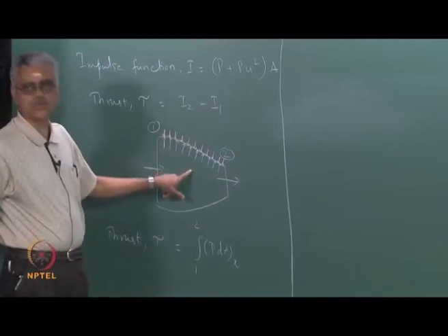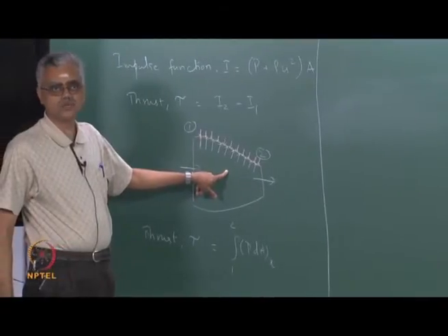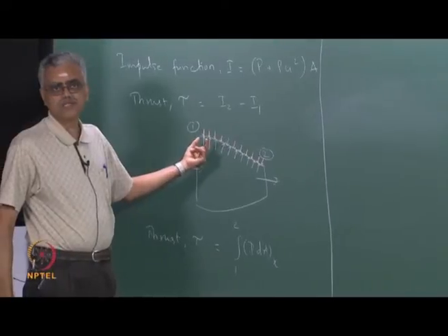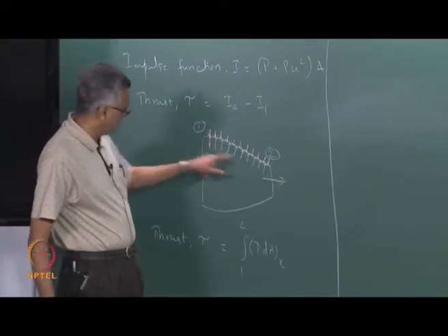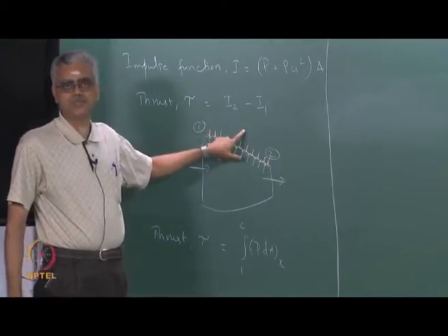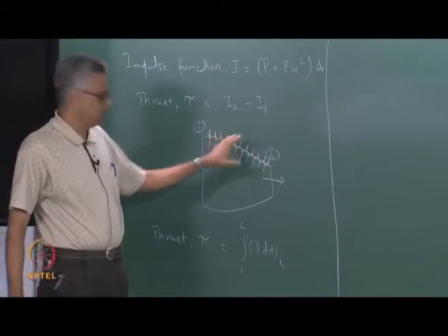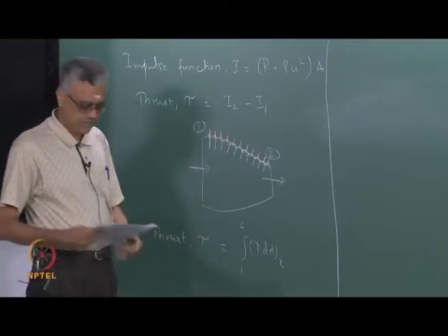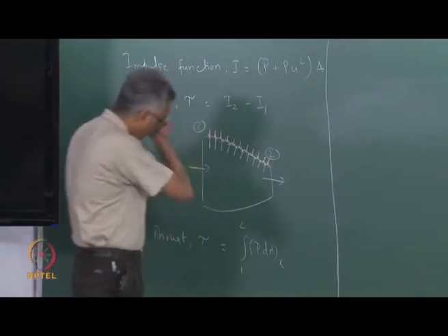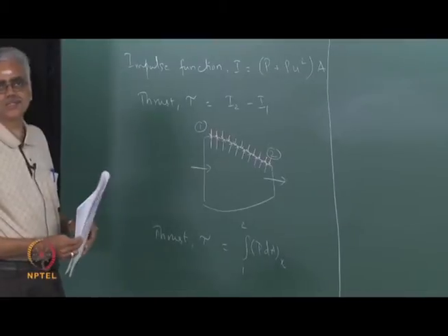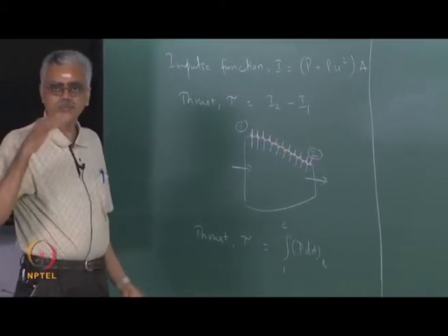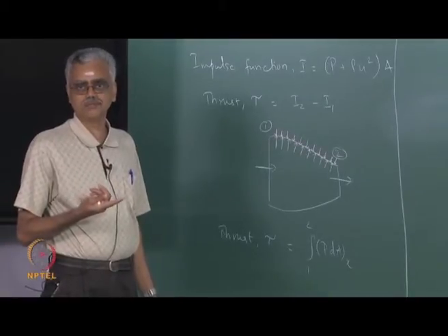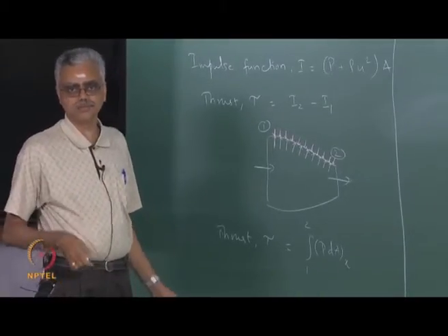So the net pressure force on the surface of the nozzle is this pressure minus this pressure multiplied by the area. So it is advantageous to actually evaluate this pressure with reference to the ambient pressure at that location, so that I need not worry about this and just take this minus this multiplied by the area, and that is an idea that we will use later on when we derive the expression for the thrust of an aircraft engine. Okay, measuring the static pressure with reference to the local ambient pressure and not the sea level ambient pressure.